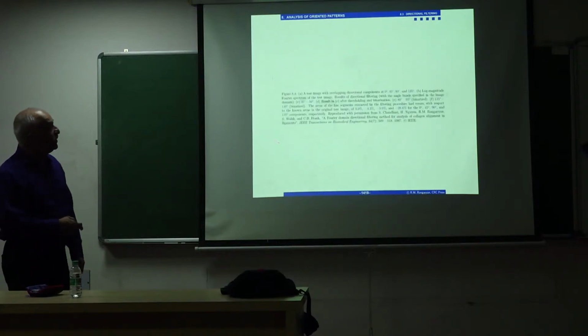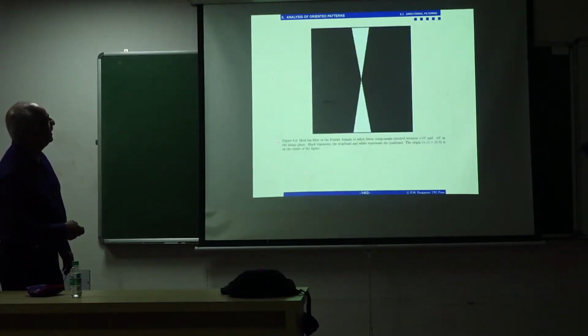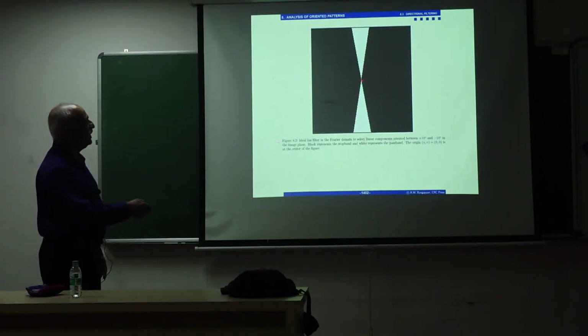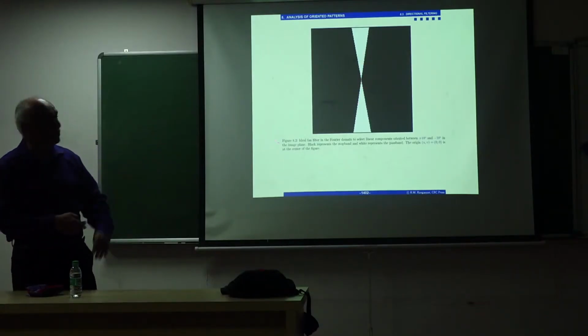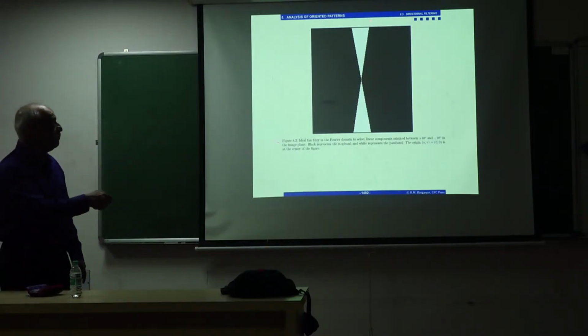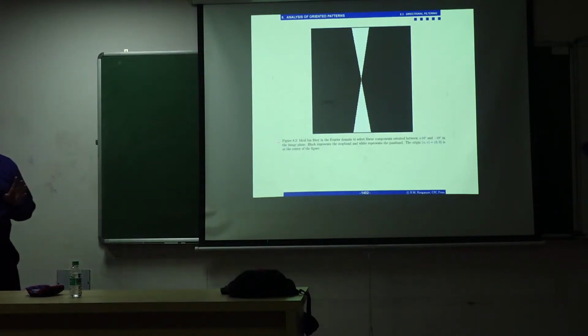But these functions, these filters, let's go back to the original. They're not continuous. They cannot be continuous in the sense of being differentiable because you want zero gain there. So if you go in this way, you want zero. If you want in that way, there has to be continuity, and there is no continuity because DC is set to zero. And if you take here, there is a discontinuity. But within the passband, you want continuity. So there are some contradictory or conflicting requirements in filter design.